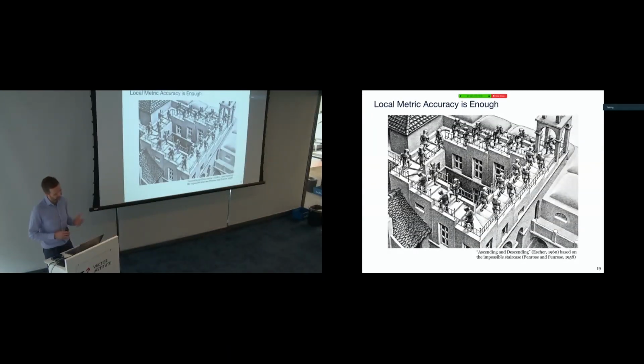And so I kind of like to explain relative map structure in the context of this picture. The idea is that we don't have any particular global reference frame that makes the whole map make sense. So it's a bit like the Escher staircase. If you just look at one of these corners, everything makes sense. Right? Locally, it makes sense, and you could use that to navigate. But globally, it does not add up to something sensible.